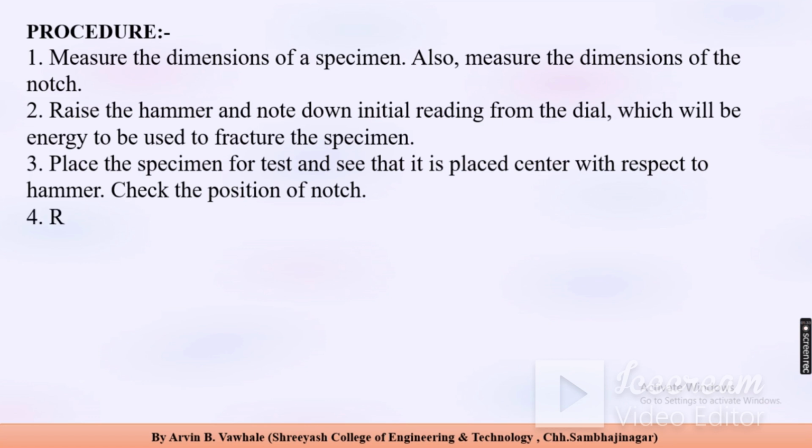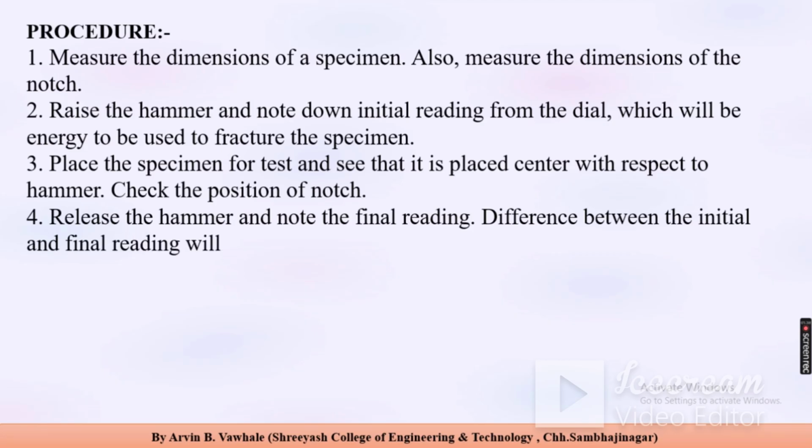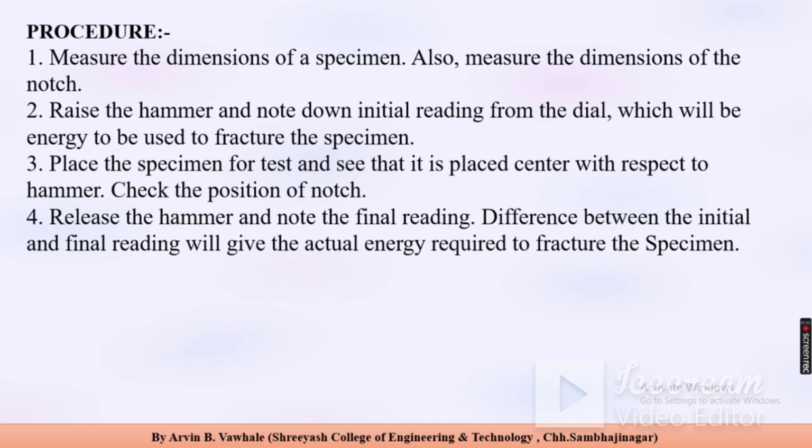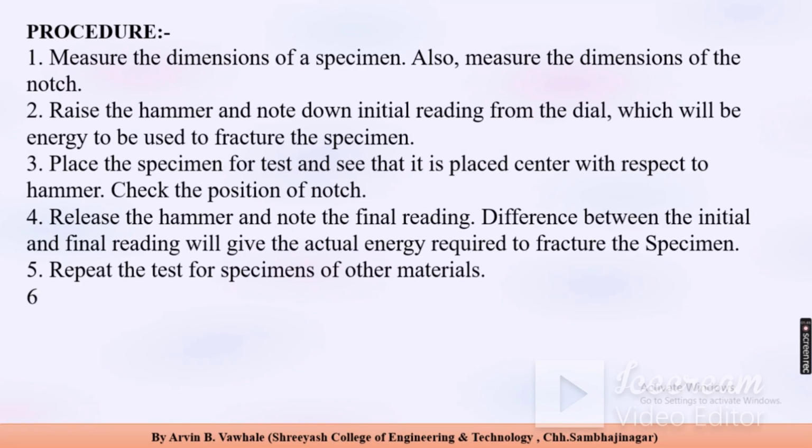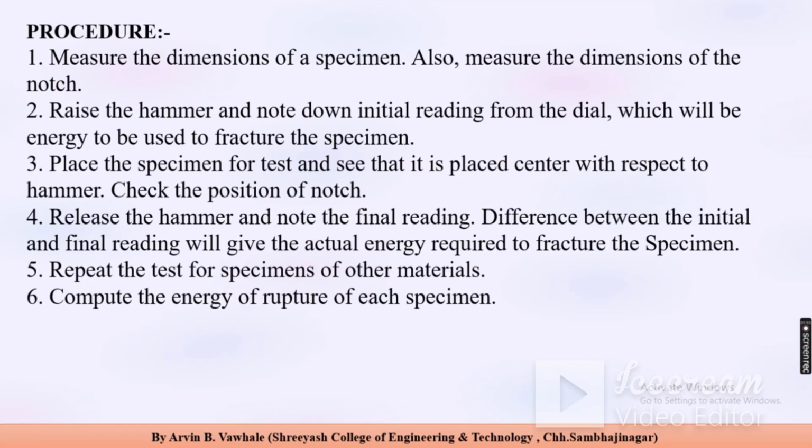4. Release the hammer and note the final reading. The difference between the initial and final reading will give the actual energy required to fracture the specimen. 5. Repeat the test for specimens of other materials. 6. Compute the energy of rupture of each specimen.